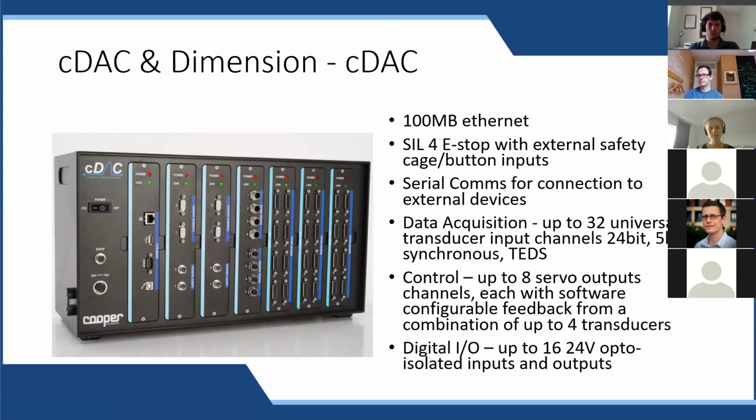It's also got some digital I/O on there. It's fairly basic digital I/O, which is all we needed, but allows us to switch valves on and off and receive inputs from users or from certain aspects of the machine. They're all opto isolated.